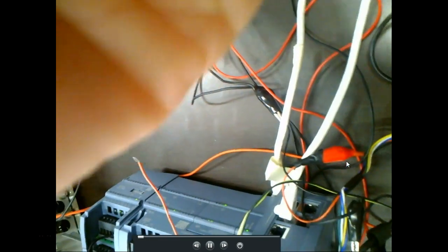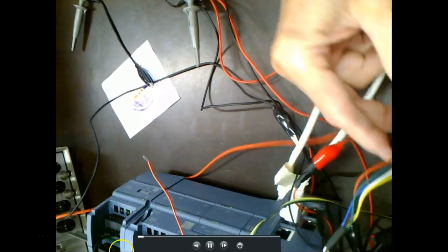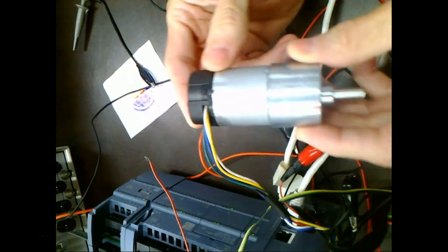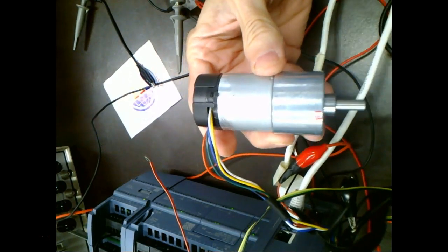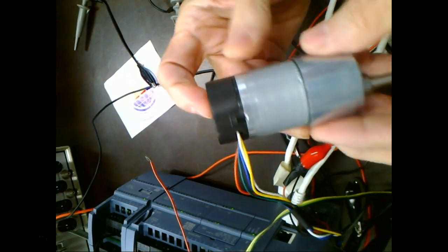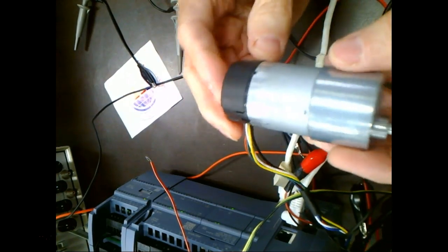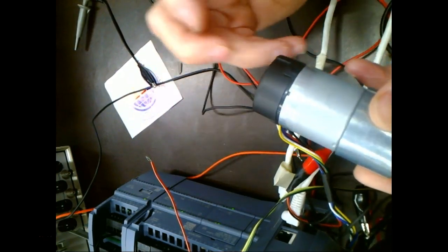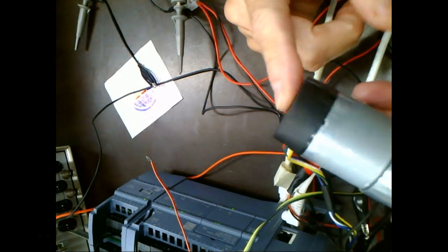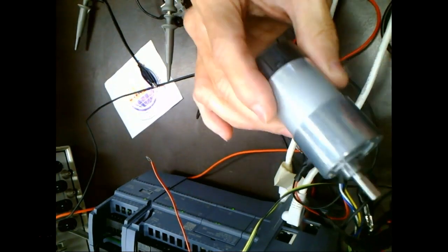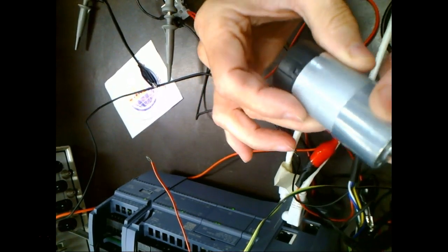So this is the little servo motors that we bought. These use quadrature encoders. It's a DC motor, but it uses quadrature encoders. It's a servo motor. So a servo motor is a motor that provides what? Feedback. The feedback that it uses is a quadrature encoder. So everything is built together. It's a gear motor, so this is the gearbox out here.